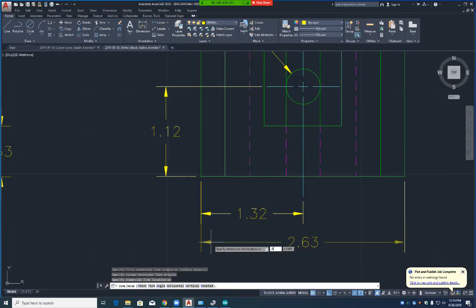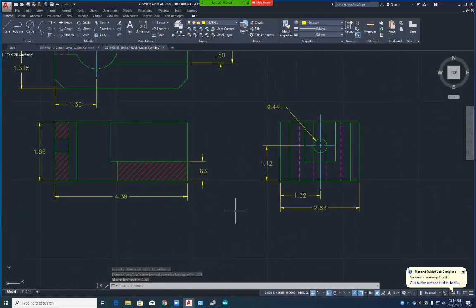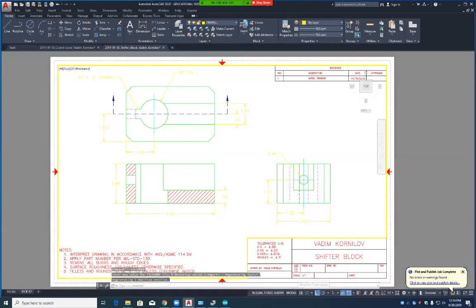So I can redimension. Because before, my dimensions went straight to the center and I didn't have my center line. So I just click from the center line. If you dimension and move that line out to the endpoint, then your dimensions start at 6/16. That's set up. So I just click and drag it, and from this dimension here, it gets snapped to 16. Yeah. Okay.